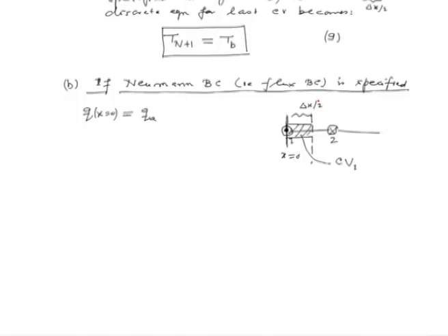So, now we have to write ab initio the equations, or we would apply our integral equation to this half width CV, and we would note down that the flux is given, that is this q a is equal to minus k dT by dn at x is equal to 0.